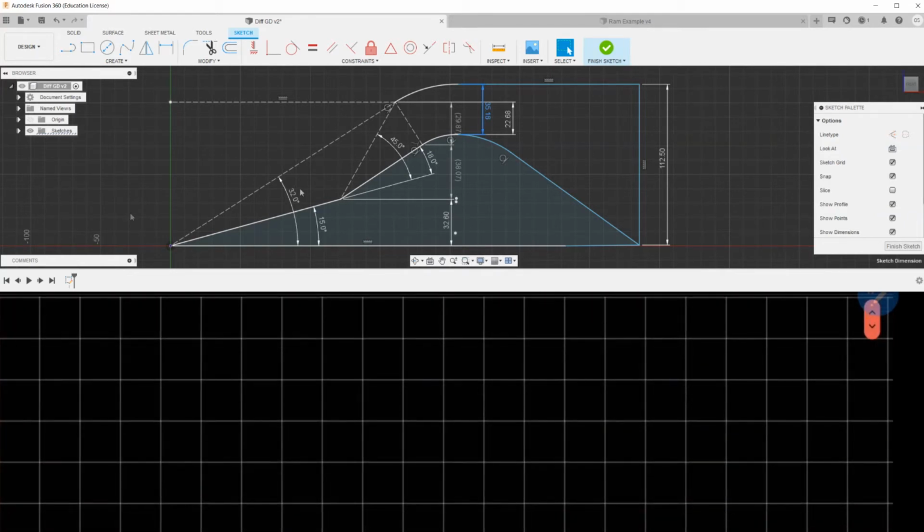So it's quite simple, as Anderson states, that we know by calculation of the flow properties the pressure on each section, inside section 1, section 2, and section 3, by our analytical calculation. And since the Reynolds number in this task is very, very big, that means that viscous forces like friction are negligibly small with respect to the pressure forces.